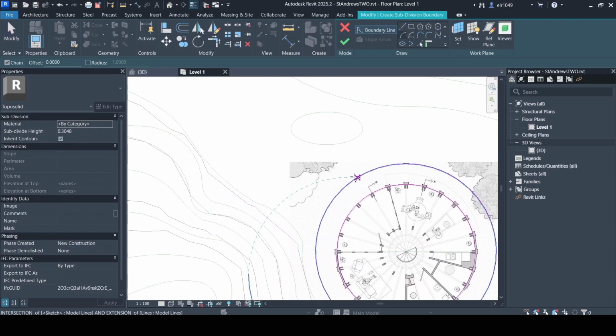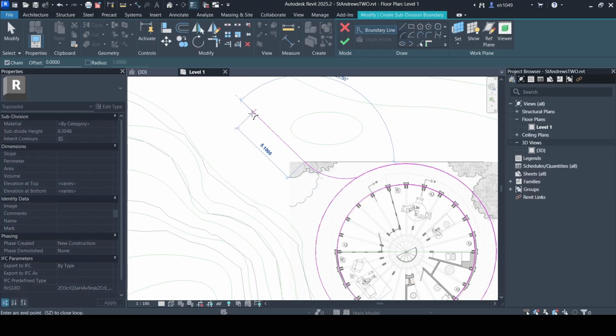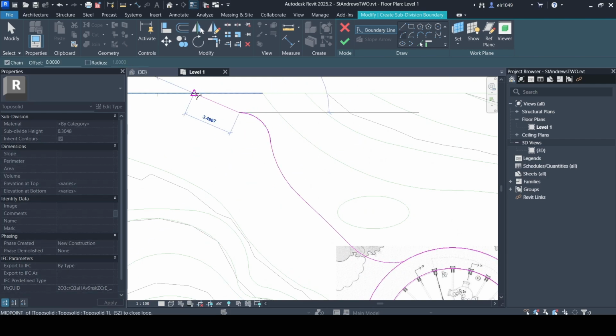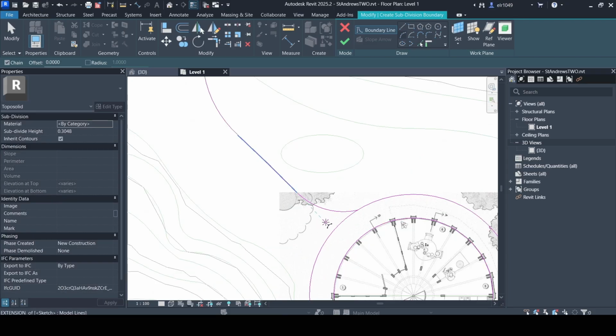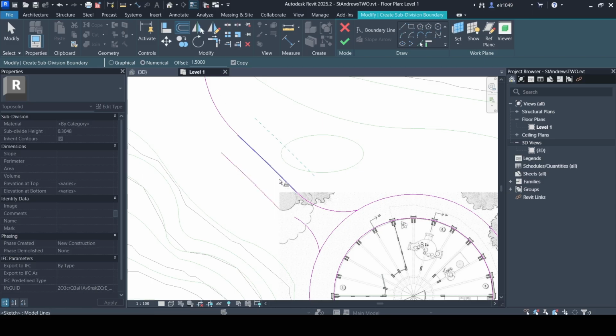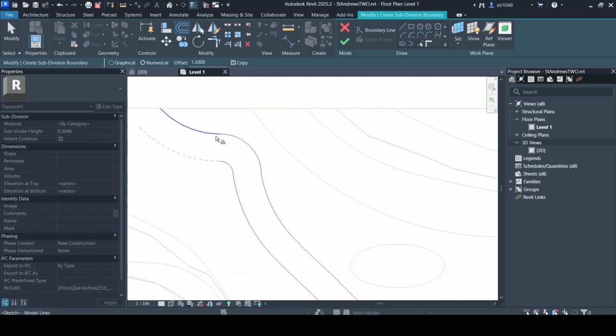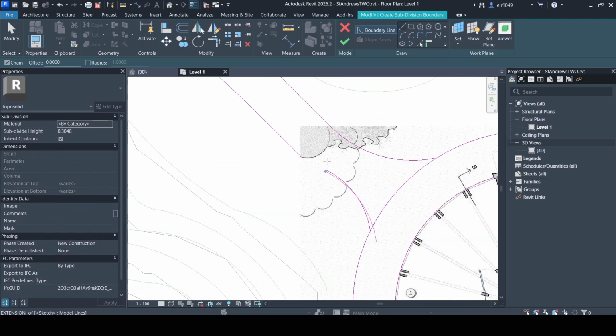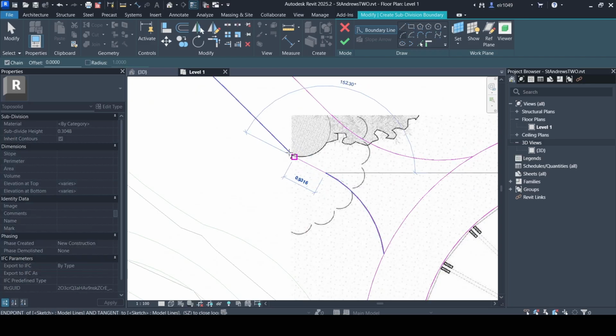Then I'll use the arc curve tool to make a winding path coming from the building out to the edge of the site. Once I've done one side of the pathway, I'm going to do this little starting curve, and then I'm just going to use the offset tool again with the same thickness as the center path around the house. And I'll finish this little corner here. Make sure to cap it off because it is similar to an extrusion and you need to connect the edges.